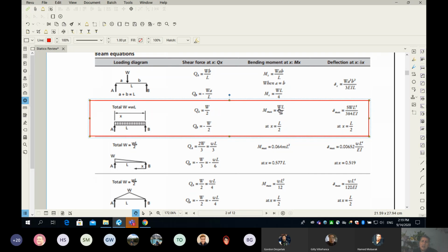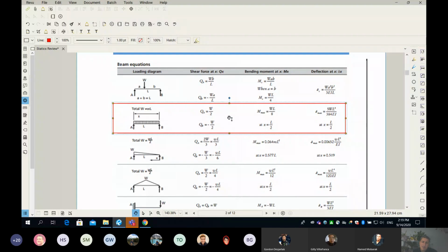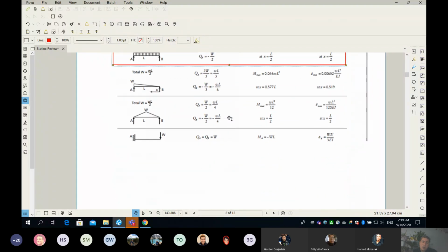And what is W capital? W capital is the total load on your beam, which is WL. I was about to say that this is supposed to read WL squared. However, it is right the same way, because W here is W capital, not like what I did, because look at the left side, W capital, which is the total load, equals the uniform load per meter multiplied by the span. Anyway, so this is how you estimate the bending moment and the shear for simply supported.